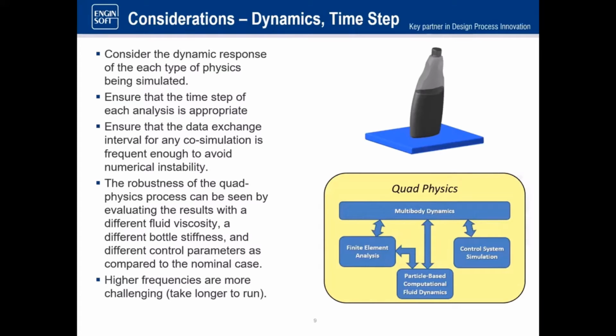So basically when you're doing multi-physics, then whichever aspect of physics is requiring the smallest time step, that's going to determine the time step, because we can't allow any aspect of the simulation to not have proper accuracy. So then we want to look and see what these different time steps are. And in some cases, maybe we can make some adjustments, or maybe this is some feedback to us that we need to change the design a little bit.